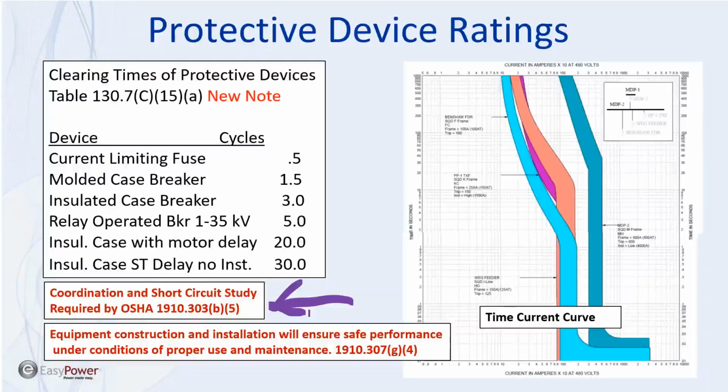So an engineer will be hired to design the electrical systems based on our specs and our loads and so forth, and they will contact the utility and find out what the available fault current is and some other data, and then come up with the ratings of the equipment according to the short circuit study. So they may say, okay, we need to get 65,000 amp rated switchgear and panels and so forth, and whatever they're going to need to do.